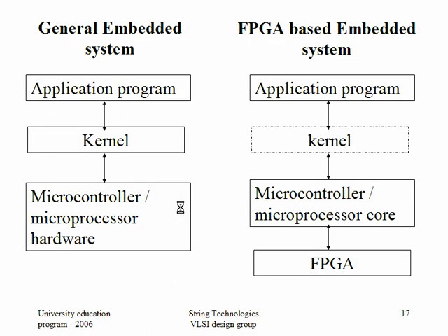Now this is the main diagram which should fit in your mind to differentiate what is a general embedded system, what is an FPGA based embedded system, especially in hardware software perspective. If I am using an FPGA, I am writing some C code, means something like this is happening. What do you mean by it? Let's see. In conventional embedded system, I will have the hardware which is generally hard implementation. No software issue. It is definitely hard implementation, processor or microcontroller.